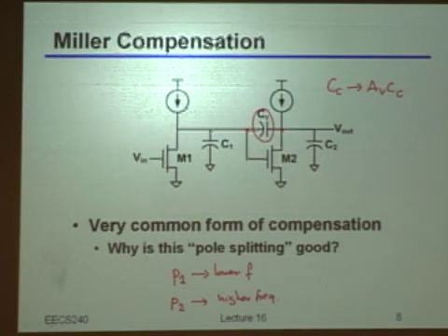Yeah, exactly. The name of the game here is the level of voltages that you have on both sides of the capacitor, right? So if we assume just a 1 millivolt signal swing there, and this stage is giving you a gain of 10, then you would have minus 10 because it's an inverting stage. In this calculation I'm just estimating without considering the feedback cap. So minus 10 millivolts.